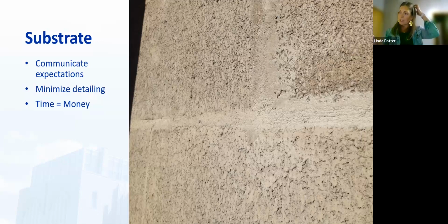This commonly happens. Here we'll just use my background, which is masonry. If the mason is laying up a structural wall, and for years and years they've laid up structural walls, what they're doing is they're either leaving the mortar however it is, because it was always thought to be structural and you're covering it up, it doesn't matter. So those mortar joints are not clean, they're not flush, they're not cut off, it's messy, or they're cutting it flush.